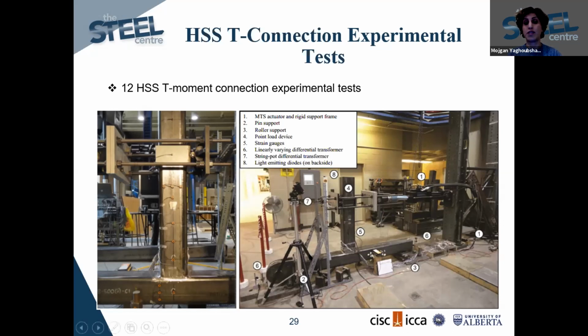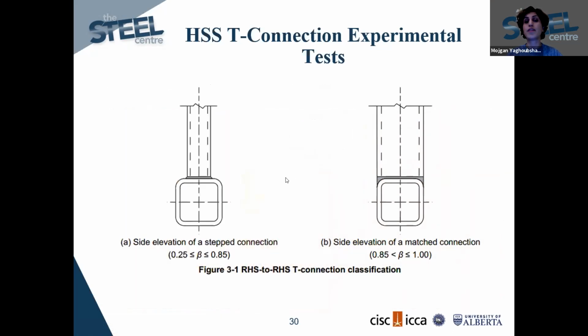These are the test setups for 12 HSS connections with different geometrical properties, both matched connections with the beta between 0.85 and 1, and step connections with beta between 0.25 and 0.85.